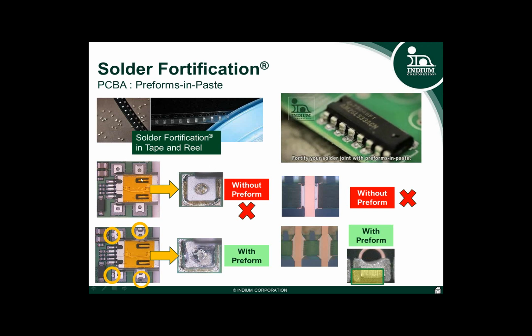This is a USB connector that's on the side of a board. It's also going to have a lot of interaction in its life, so it's going to have a lot of plugging in, plugging out. We need to add the additional solder volume here as a mechanical feature, just to stop that wear and tear on that connector causing an open circuit in the lifetime of that particular piece of equipment, making it a little bit more robust in its application.